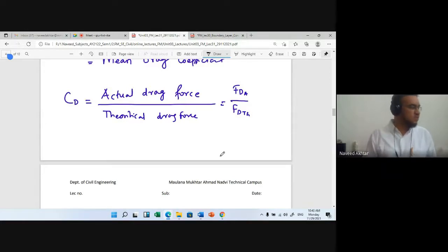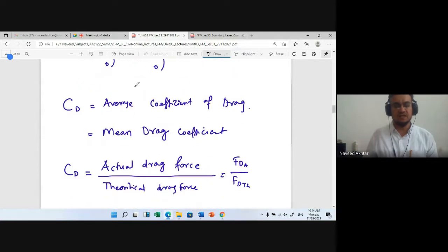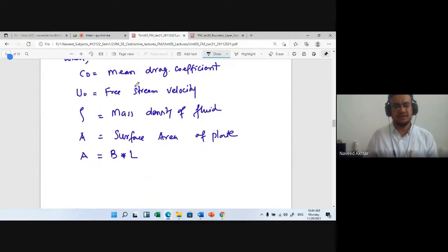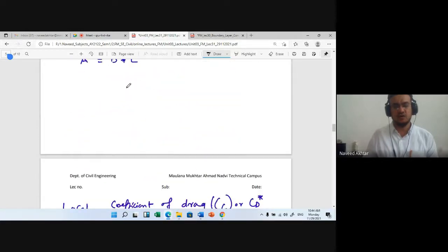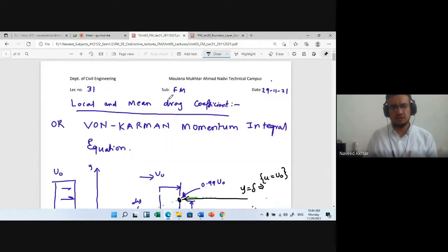So you have to learn this using the von Karman momentum integral equation. From that we can derive the average coefficient of drag or mean drag coefficient CD, that is, the local drag coefficient CF or CD star. So today's lecture is based on the local and mean drag coefficient.